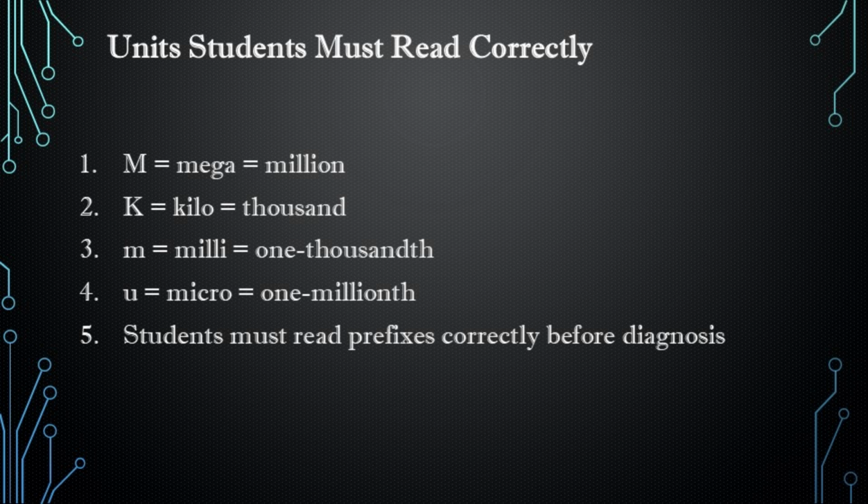Now this sounds basic, but this is one of those areas where students can make real mistakes. If a student confuses millivolts with volts or kilo ohms with ohms, the number on the display may be correct, but the interpretation will be wrong. A voltage drop of 0.2 of a volt is 200 millivolts. Now, that is not the same as 20 millivolts. 1 kilo ohm is 1,000 ohms. 1 mega ohm is 1 million ohms. Those are major differences, and the diagnostic conclusion changes with them.